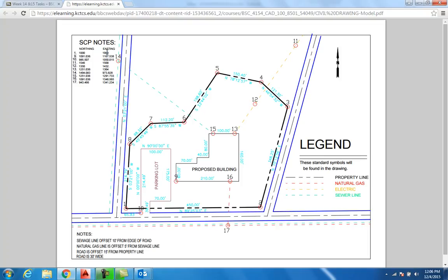And if you're using state plane coordinates, or state coordinate planes, whichever way you want to say it, there always is an origin in every state, your 0, 0, and sometimes states are divided up. Now Kentucky, you can use the single state plane coordinate and there's one origin, or you can use the north, and they have it split up in two halves, the south and north, and they'll have two different origin points. So that's something to remember.